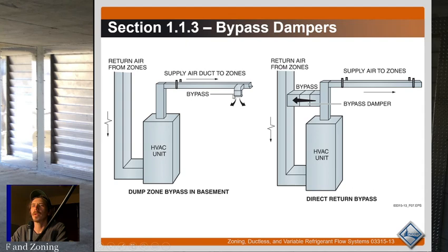Well, once you get to a point where the pressure exceeds what the fan is designed for, right? Because typically this is going to be the upper limit of the design. So as the pressure or the head pressure on a pump motor, or the static pressure in the HVAC system for most residential systems, between 0.8 and 1 inch of water column. Once you start hitting that static pressure, the fan can no longer do any more work, right? That's the most work it can do. You've exceeded what it is capable of. And once you hit that kind of soft peak, everything drops off. Okay, so you've got kind of a slow climb.